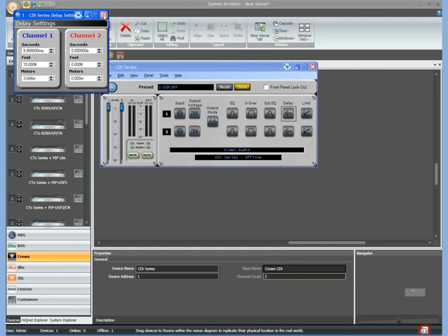I would most likely not want to have two different sets of delays in this case, but I might want to use two different delays if I had two different clusters of speakers and I wanted to align them to each other, or to a third set of speakers if I had multiple arrays. In most cases, you've got a subwoofer and a satellite, and you simply need to adjust one to the other. So you pick the one that you're closest to and delay it to adjust it to the one that is further away.